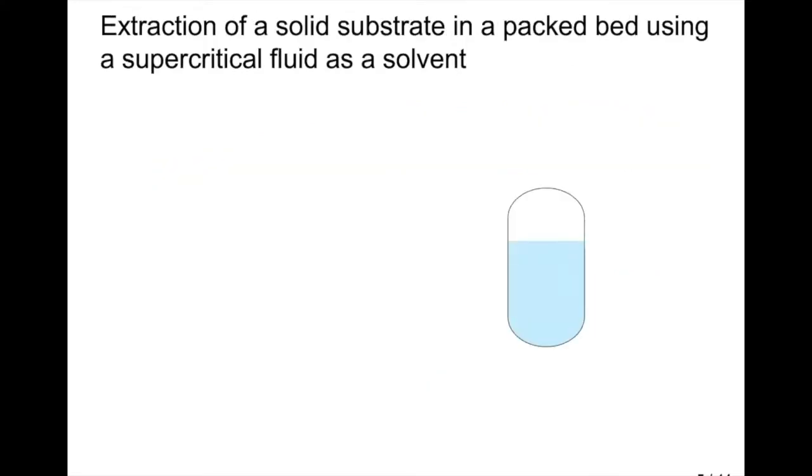In a supercritical extraction pilot or industrial plant, the CO2 flows in a cycle. CO2 is stored in a working tank at the saturation condition at the environmental temperature. To reach the desired conditions within the extraction vessel, the CO2 stream is subjected to cooling, pumping, and heating or cooling.